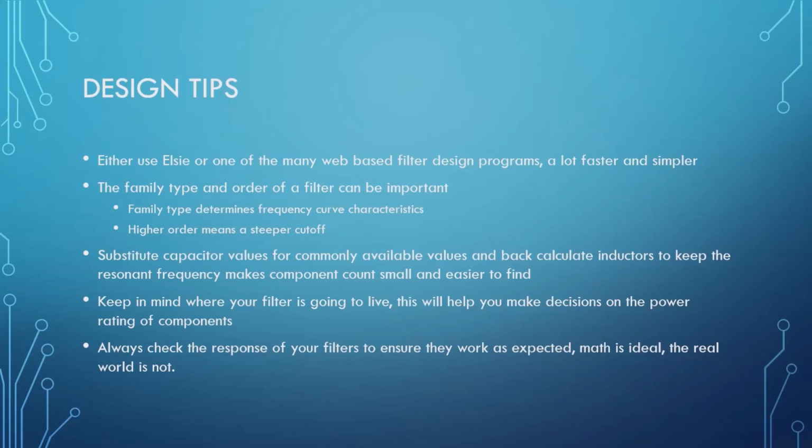So most capacitors are 5%. So a lot of your things, your frequency of resonance is going to be plus or minus a few percent, kind of thing like that. Right. Well, and another thing is that you can't really use just standard capacitors for this. Normally you want to use NP0 capacitors or mica capacitors for RF, so that they've got a much smaller tolerance, and they basically, at frequency, their capacitance will be what they're rated, or what they say they are.